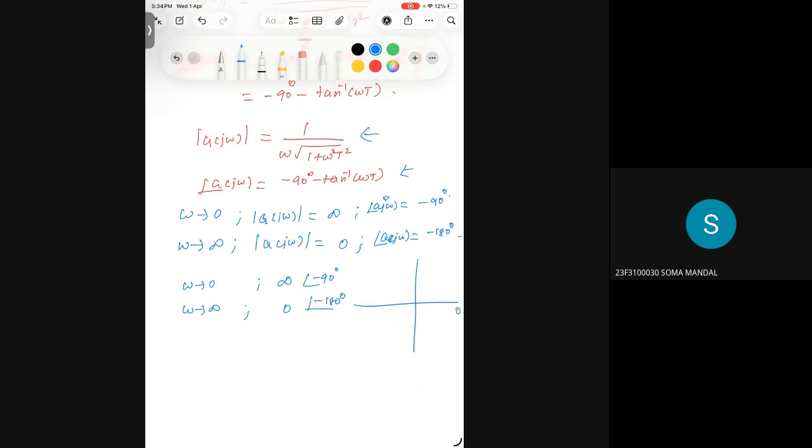So if I write 0, 90, 180, 270, minus 90, minus 180, minus 270, then it starts at infinity at an angle of minus 90. So from here, somewhere in the infinity, okay? It starts from here, so the arrow would be like this, and it ends here. So I will write in this direction. So it will be easy. It ends in the third quadrant. From infinity, it ends somewhere here at 0 at minus 180 degree, third quadrant.